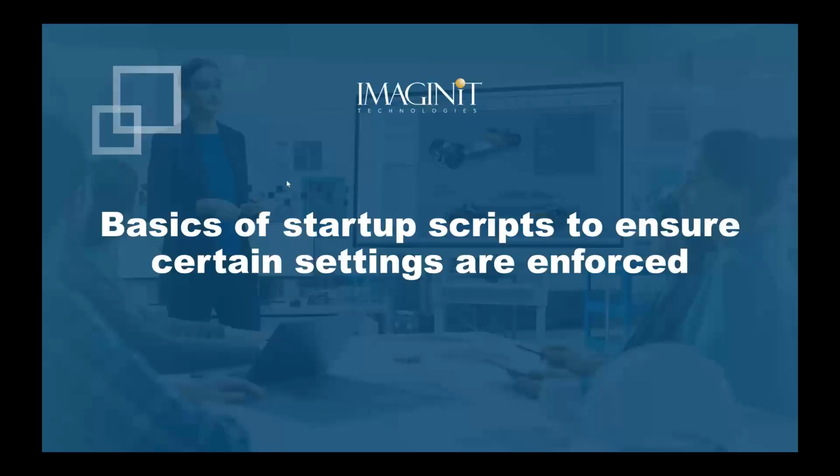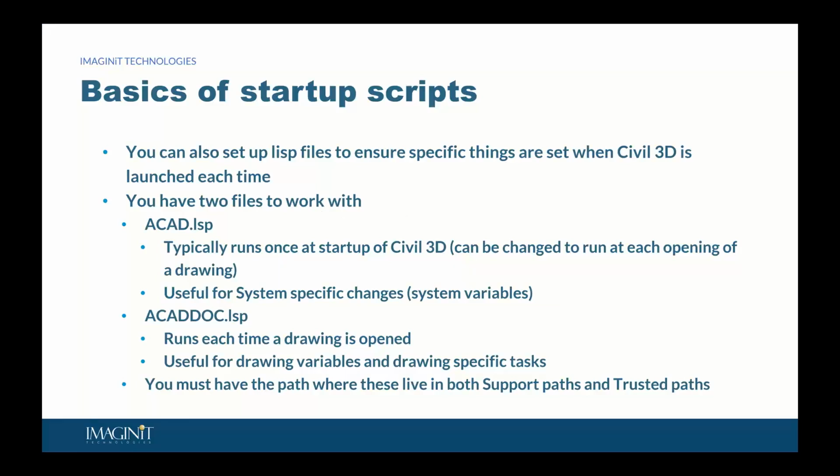So once we have our ARG file in place, now we can start talking about a startup script to ensure certain settings are enforced. This is one of the things I like to do. Provided I have a support path that points to where the Lisp is located and I have it in the trusted path, I can create two additional files, and these are just standard text files. The first one is an acad.lisp. This will typically run once at the startup of Civil 3D. It can be changed to run at each opening of a drawing, but I usually like it to only run at startup. It's useful for system-specific changes, system variables, updating paths, changing support file paths, etc.